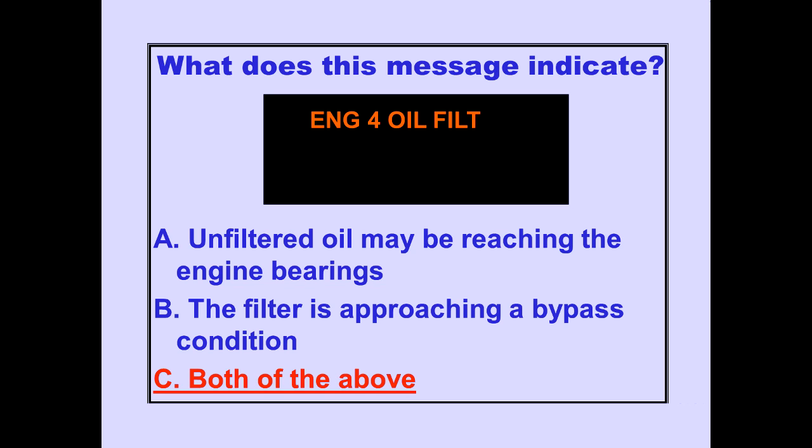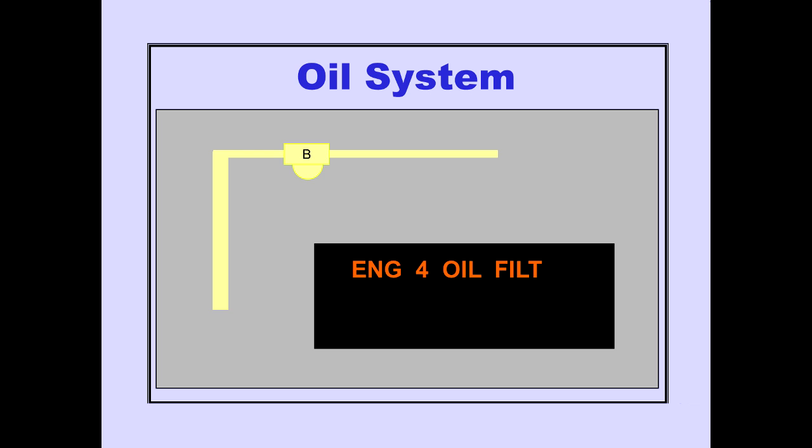Answer C is correct. The message is displayed when a bypass condition approaches and will remain if bypass occurs. Reducing thrust on the affected engine may minimize bypassing unfiltered oil.